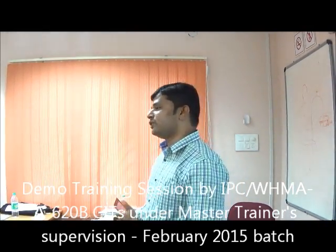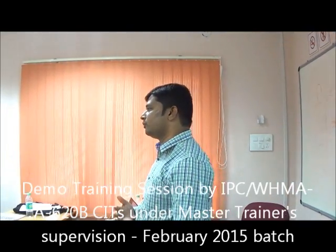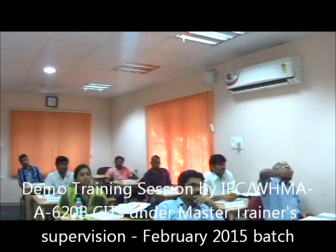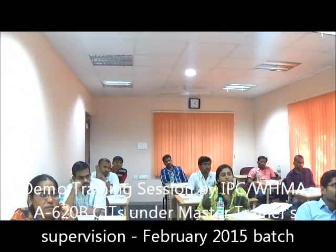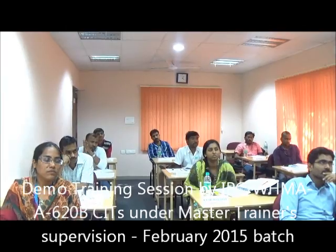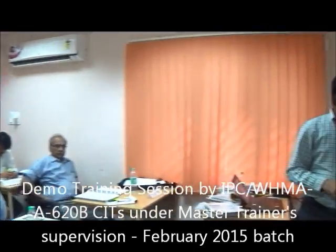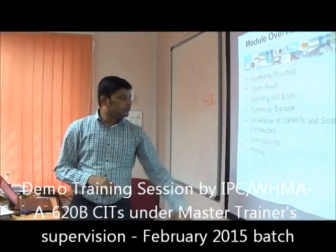So what is the purpose of using the seal plugs? It is to prevent foreign object debris, FOD materials, from entering into the connector. The second reason is during vibrations. We should install the seal plugs. And then over molding.